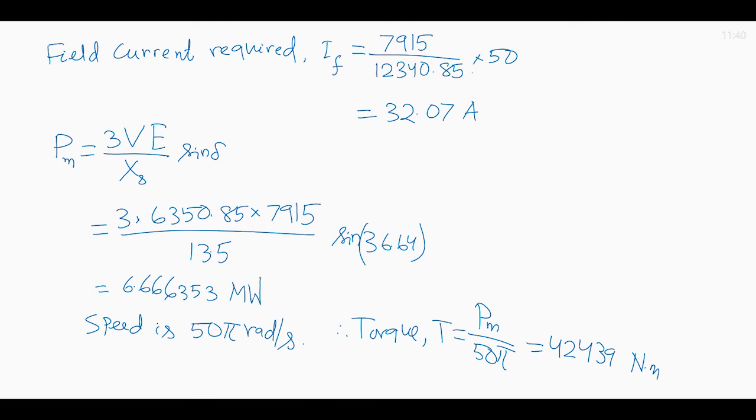36.64 degree. So, if we draw the phasor diagram for understanding, voltage V is the reference, with unity power factor stator current. So, IS is here, the stator reactance drop jXS IS is like this, and this is the induced EMF E, and this is the angle delta. So, delta magnitude is calculated because induced EMF rotates ahead of the supply voltage.